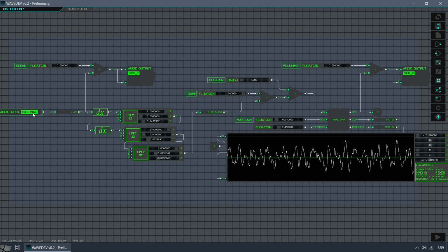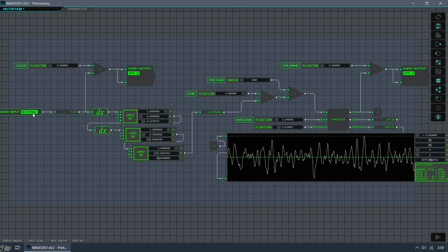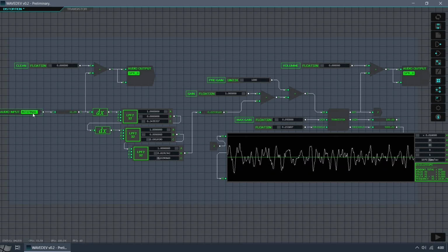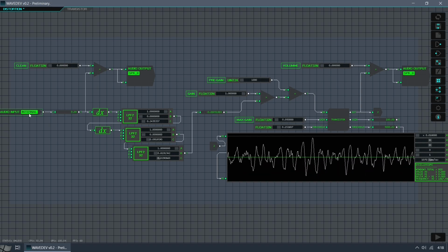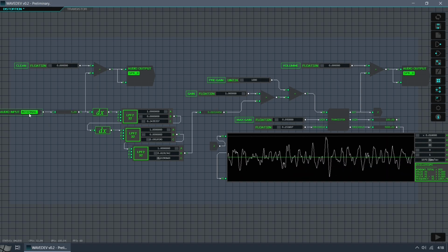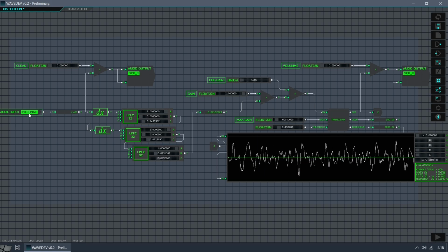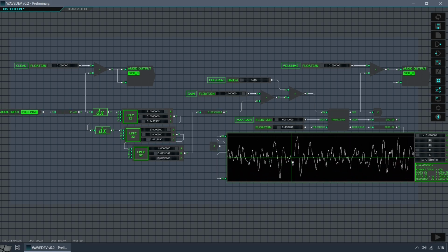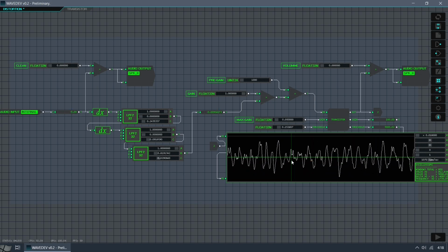But decreasing this gain knob will reduce the resolution of our sample in the system, and that will lead to a loss of quality. So I'm going to consider this last case as the most common to propose a third option. This will be the definitive solution to the noise problem. I'm going to use an external low-noise preamplifier.